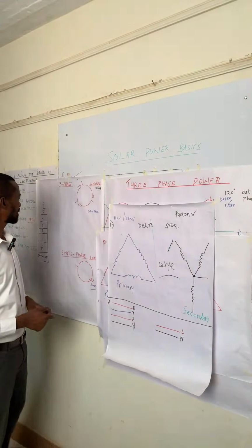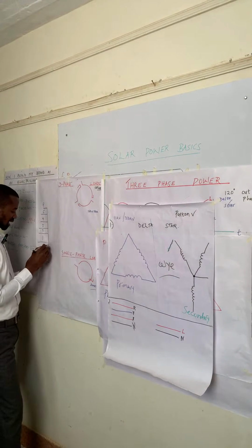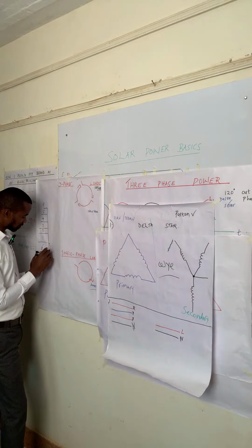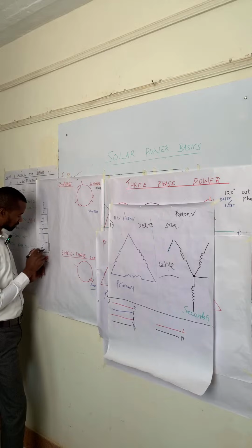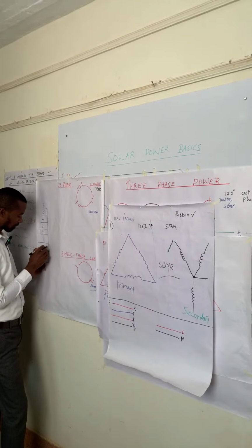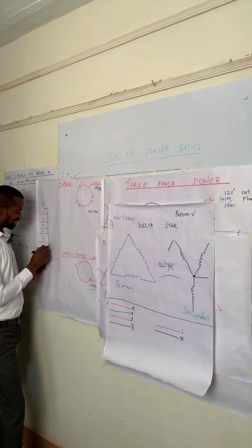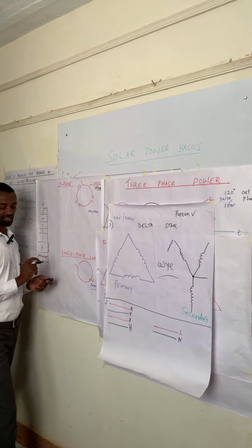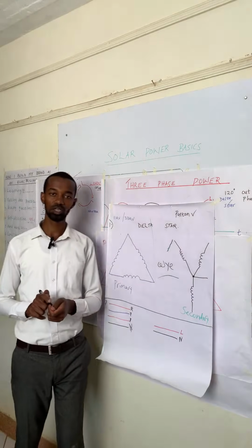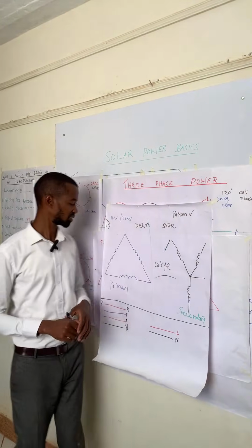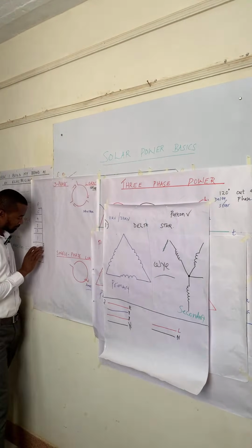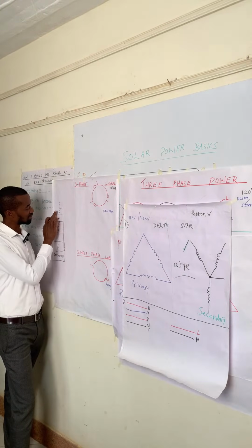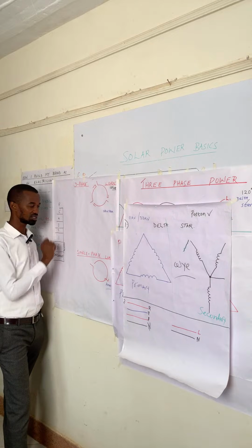So now at the meter board of this commercial apartment, it could be at the ground floor or it could be at first floor, but in most cases it is ground floor. Now you find that there are several energy meters here. All these energy meters are usually single phase. And then this board carries each and every meter that feeds power to all of these houses.